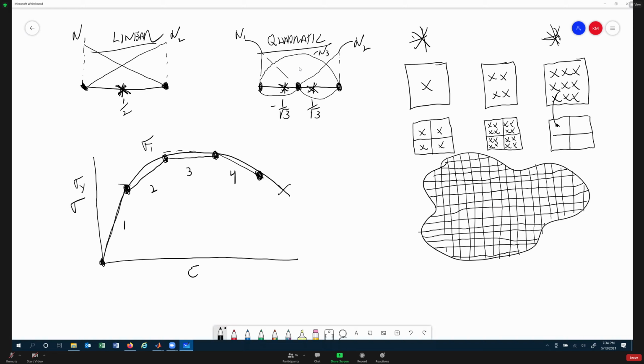But the point is there's a balance. And what you want to do is start off with something very simple that's fast, that you can actually get a solution with. And what you're looking for, to make sure you actually get a solution, is, one, does your software system error out? Does it give you a free body motion or a Jacobian error or something like that that tells you that maybe you have a problem with your setup?